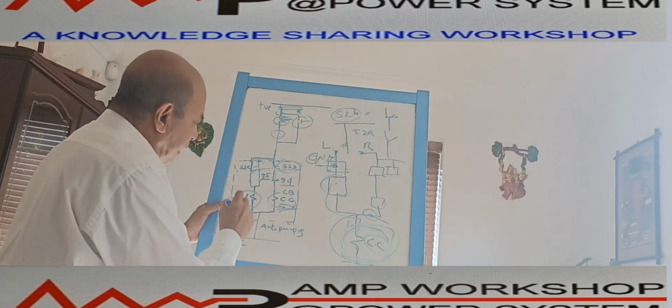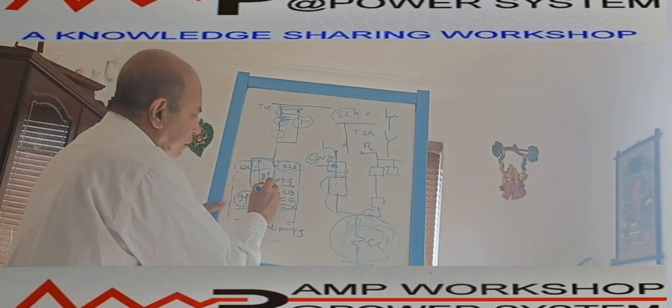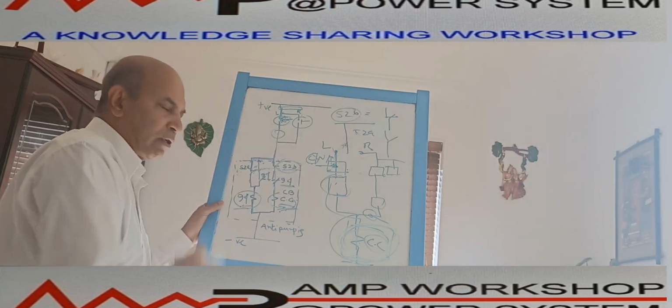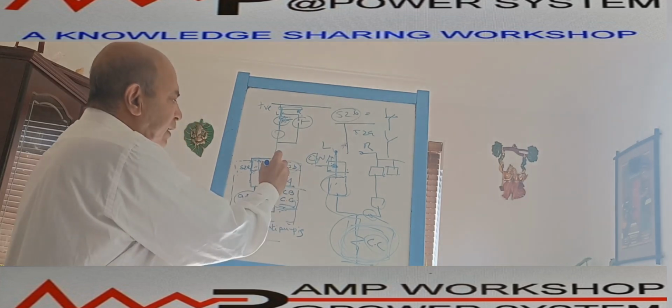The moment the anti-pumping relay is picked up, immediately it has auxiliary contacts. You see, there is one contact over here and another contact here. This contact is an NO contact and this contact is an NC contact, which is connected to the closing coil. The moment the anti-pumping relay is energized, immediately this becomes open. This becomes open and this is already open. So what will happen? This power is cut.